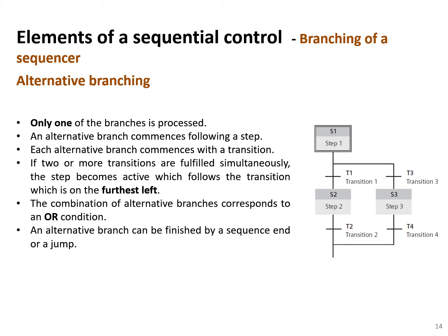If two or more transitions are fulfilled simultaneously, the step becomes active which follows the transition that is furthest left.